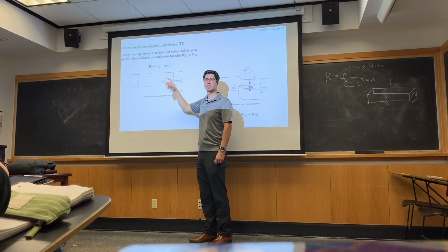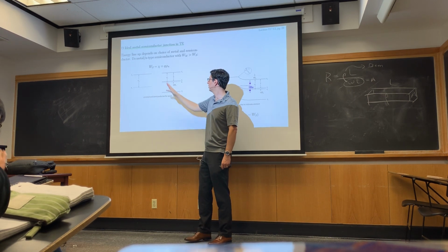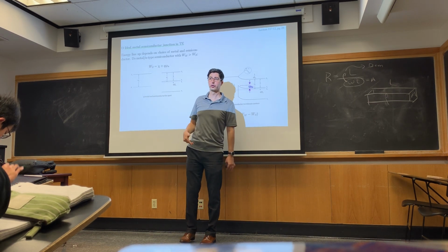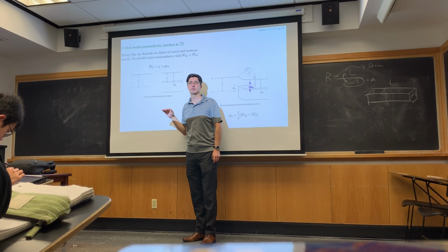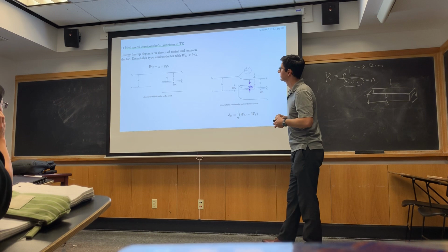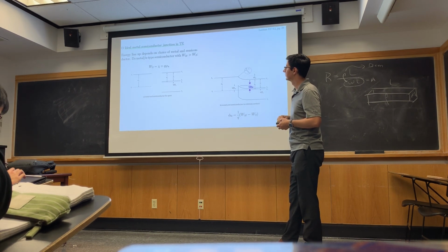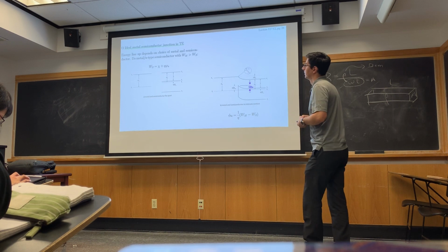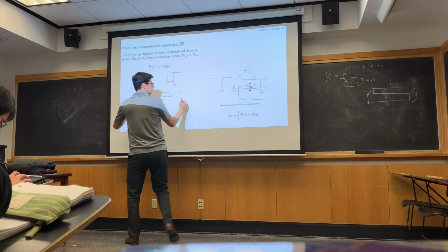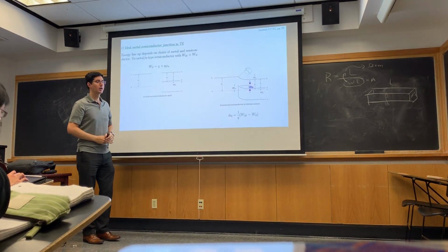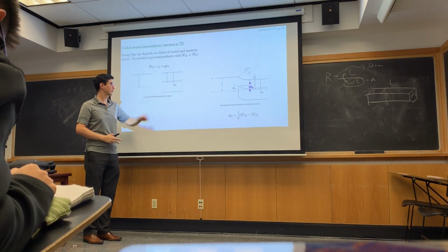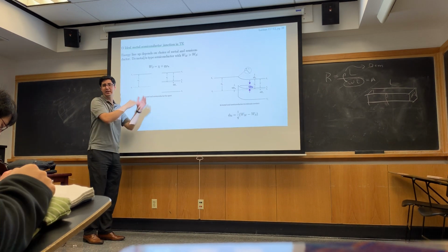And remember, Ws is always defined as a positive quantity. All work functions are defined positive. So the larger the work function, the lower the Fermi level. Okay, so when I combine these, what's going to happen? I can see that they're not combined yet because they're not in thermal equilibrium with each other. They have different Fermi levels. When I push these together, what's going to happen?